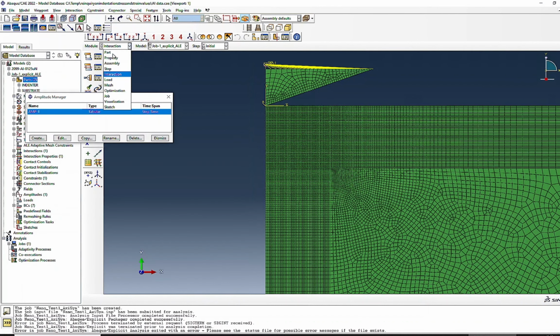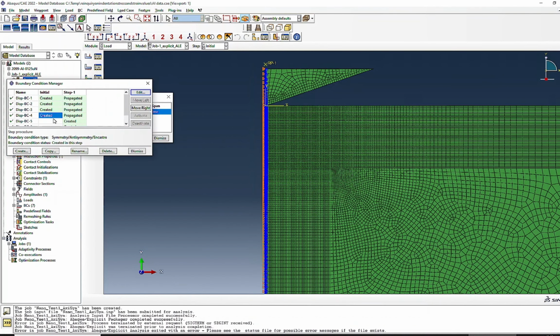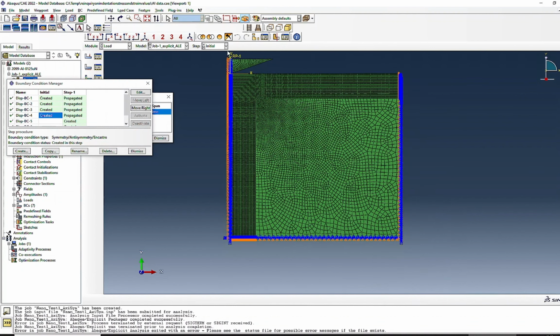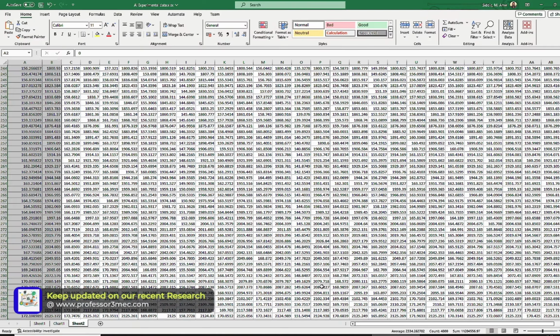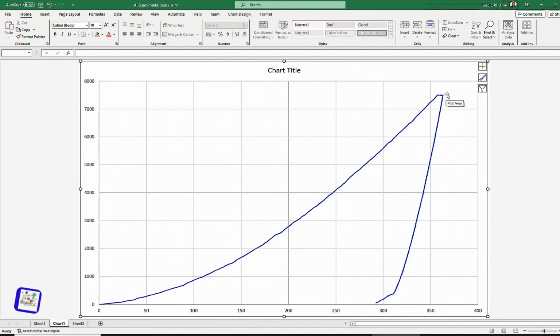And then in the loading, we have the forces, and then we have displacements and also x and y symmetric. So y symmetric, x symmetric, and then fixing this in lateral direction while moving it down with a maximum displacement of 0.39365 or something, and then coming back, bring it back to 0.3.